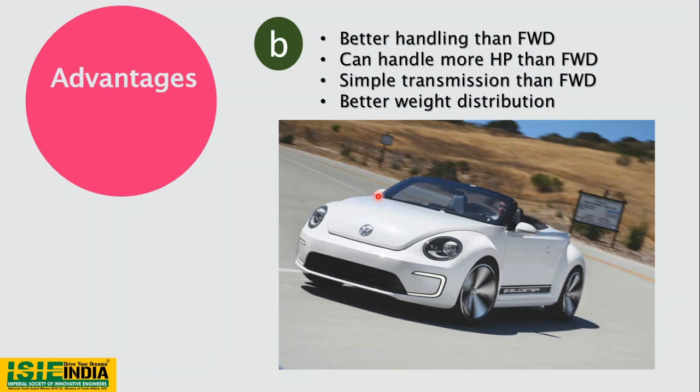But if it is placed at the front, there is plenty of squeezing of components to put the power to the front wheels. As there is a differential placed beneath, we have some solid shafts and some wheel assemblies, so it's going to almost distribute the weight. So there could be some 5 to 10% change in weight distribution, plus or minus, depending upon the configuration.